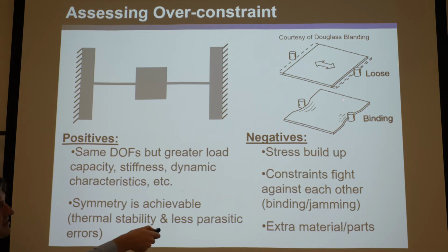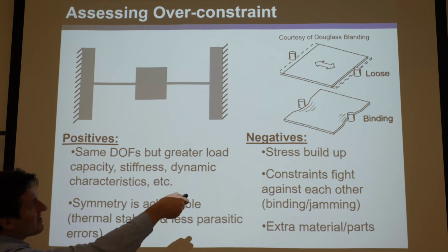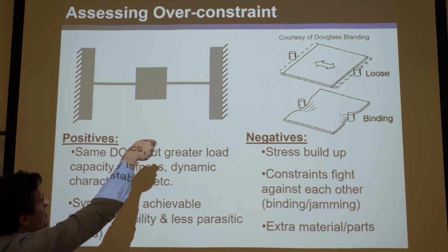This is why it's clear these are two different pegs in a board. You assembled this. It's clear for you to visualize. That's going to be a problem. But this guy, say you cut out with a wire EDM, you could say, well, I didn't have to assemble it. It's actually one sheet, and I cut it, and so maybe it is perfect. Well, wrong. Every material has residual stress built in it. When you cut it out, that residual stress will be released, and maybe this guy will expand or something more